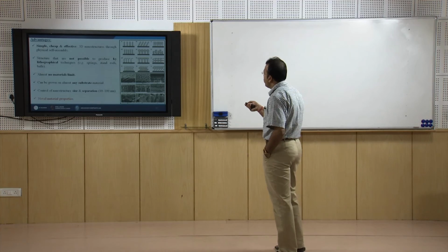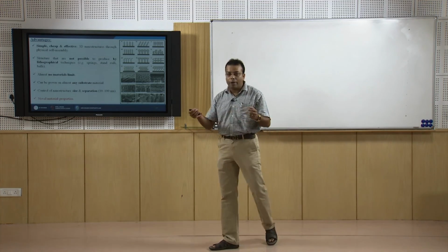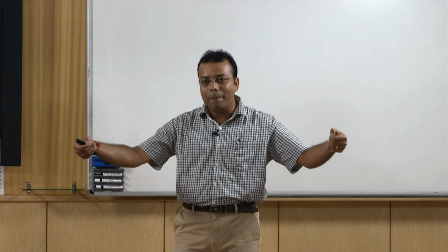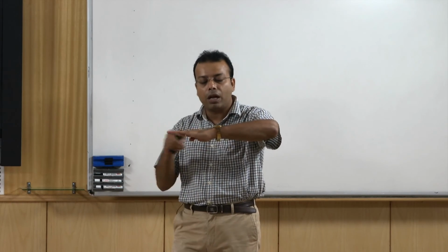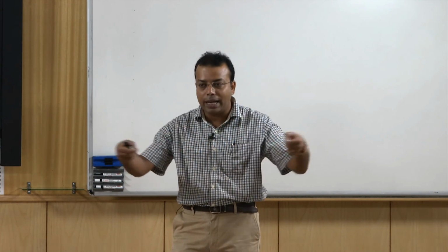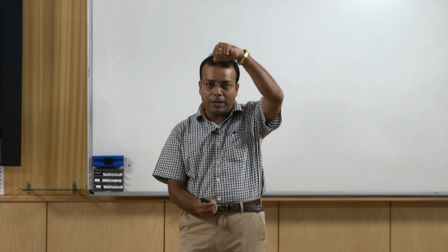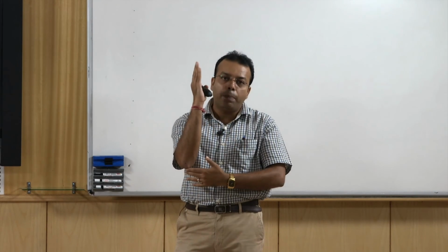So, from this particular figure you can see that depending upon our requirement, suppose I want to stretch my material like this. For getting the maximum properties I can do the coating in this direction, meaning our columns will be in the horizontal direction, so that I can achieve the maximum properties. If I want to achieve the maximum properties in these directions, then maybe I can do the coating in these perpendicular directions.